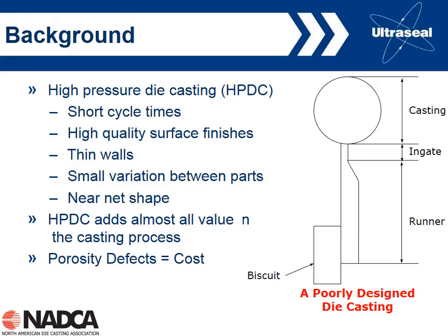So sand casting, permanent mold casting, investment casting, lost foam casting, all together only make up 1/3, while die casting alone makes up the other 2/3. So obviously, again, it's a very popular process. Why is it popular? Obviously, we've shown here, short cycle times, gives you high productivity, tends to be low cost. In fact, quite often, a lot of castings are converted from slower processes, such as sand casting.